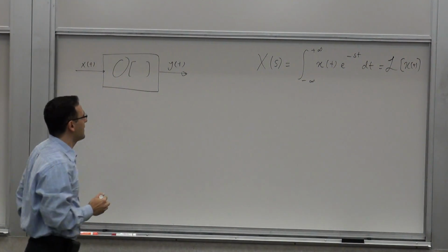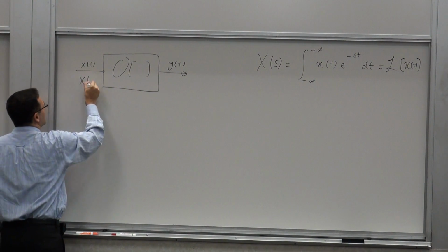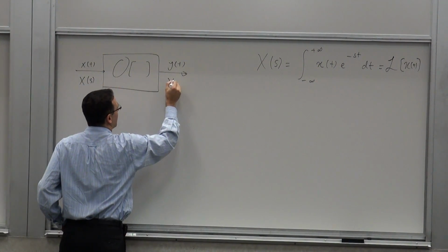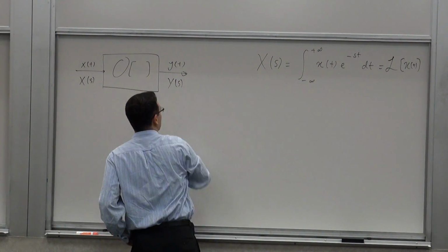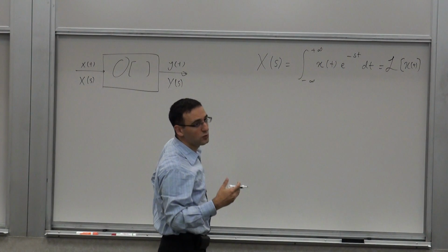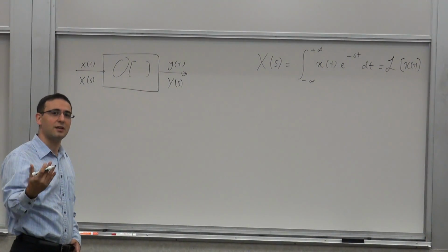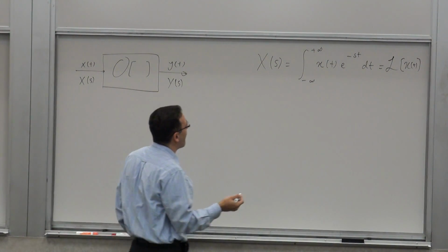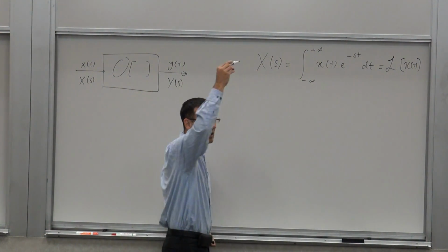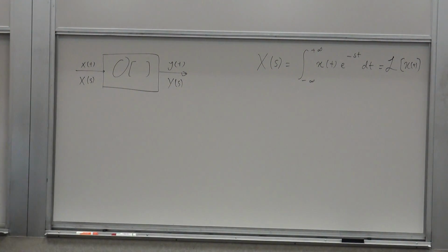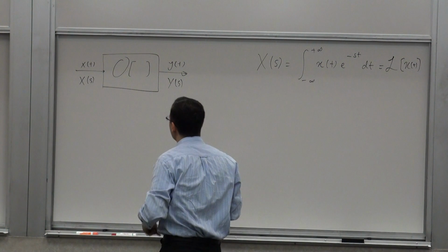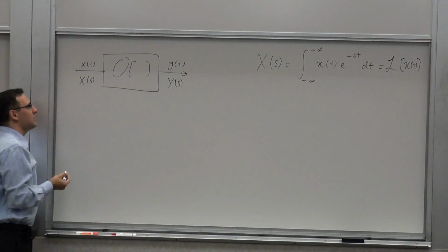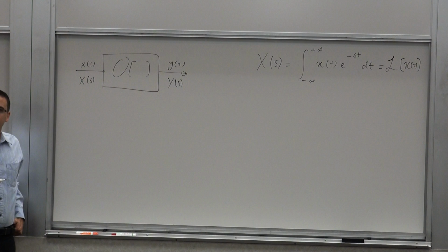So in the Laplace domain, in a frequency domain, this is a general frequency domain, right? You have an input x of s and an output y of s, corresponding to x of t and y of t. Of course, you know that if you want to go to the kind of frequencies that we typically talk about, you can evaluate it on the j omega axis, with sinusoidal frequencies. We'll see what the general s complex frequencies mean. So this is basically a complex quantity. Now if you have something like this, I'm interested in determining what y of t is in terms of x of t.